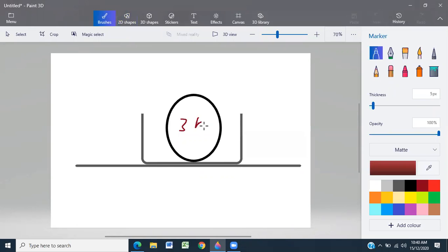Okay. So let's pretend this mass wasn't here and it was just the tray and the ground. So we know the coefficient of friction is equal to the force required to move the tray, to overcome the friction, which would be F, and that varies with respect to the weight.